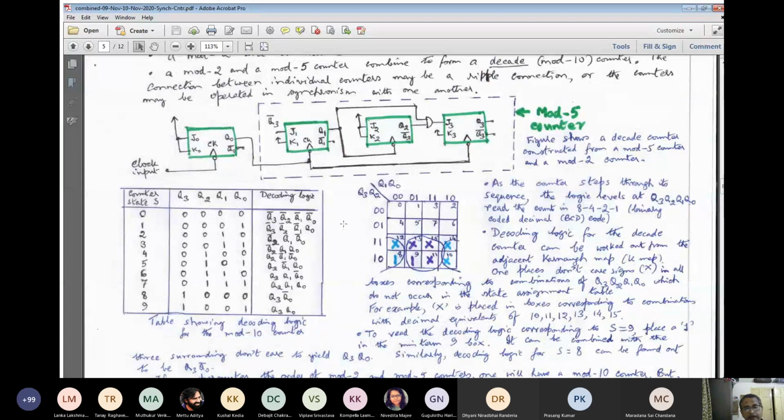Then, for the controller, you can have a hardware control unit or a microprogram unit. For a hardware control unit, definitely there will be a counter at the heart of the controller. When that counter goes from state to state, some action or other will be performed, like obtaining data from a specified memory and issuing out control signals, like storage of intermediate data to a particular register, or to a particular tertiary or secondary memory.